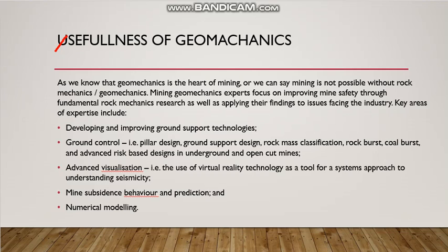The key areas of expertise include developing and improving ground support technology and ground control, which include pillar design, rock support design, rock mass classification, and problems like rock burst, coal bumps, etc. Geomechanics is also useful in advanced visualization, the use of virtual reality technology as a tool for a systematic approach to understand seismicity. It is also helpful in predicting mine subsidence, and it is useful in numerical modeling.